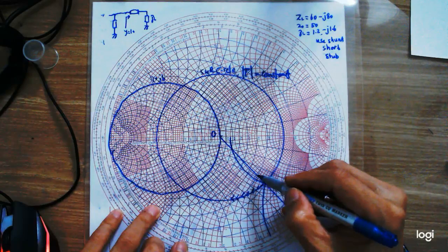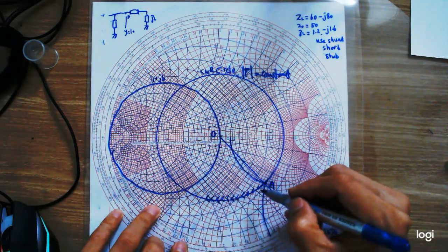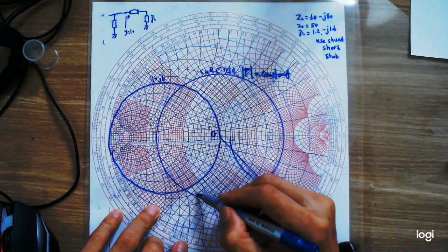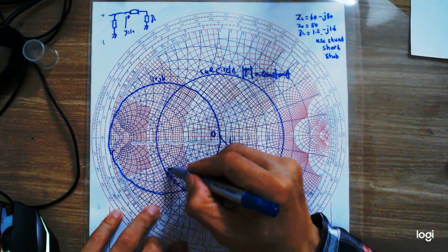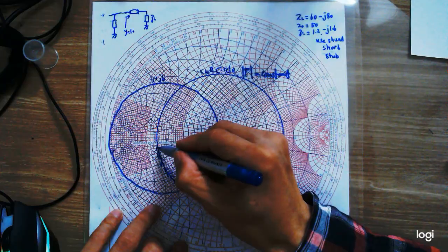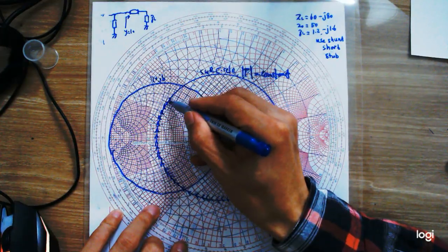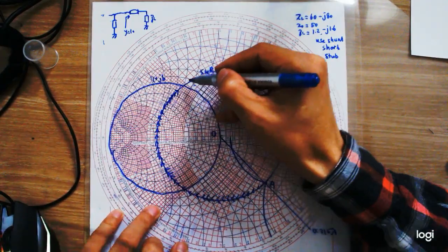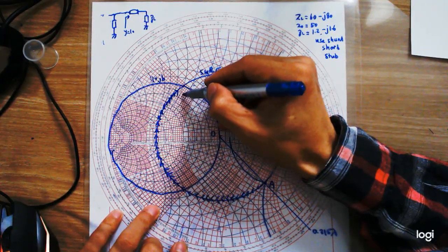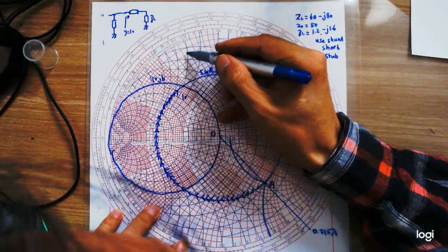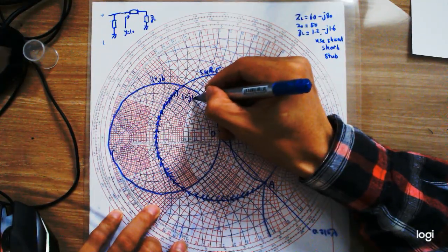We will drag along the SWR circle in a clockwise direction. The starting point is A. We always use clockwise direction. And we don't stop here, we'll just continue. So here we go. We meet the point here. The impedance at this point is 1 plus, according to here, minus, actually not plus, right? Minus j1.4.